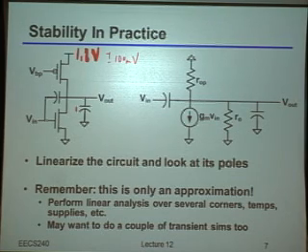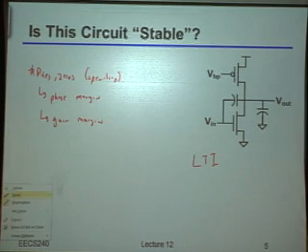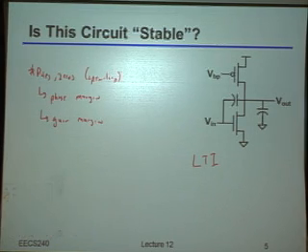Okay? And in fact, if you really want to make sure the thing is stable, which by the way is now a method I'm going to add to the list because this is actually really what you should do. The only, I shouldn't say foolproof, but the only really, truly correct way of checking these things is actually to do a transient simulation. Okay? Because the advantage of doing a transient is that now, even if it's nonlinear, it's time varying, you can just capture all of those effects.